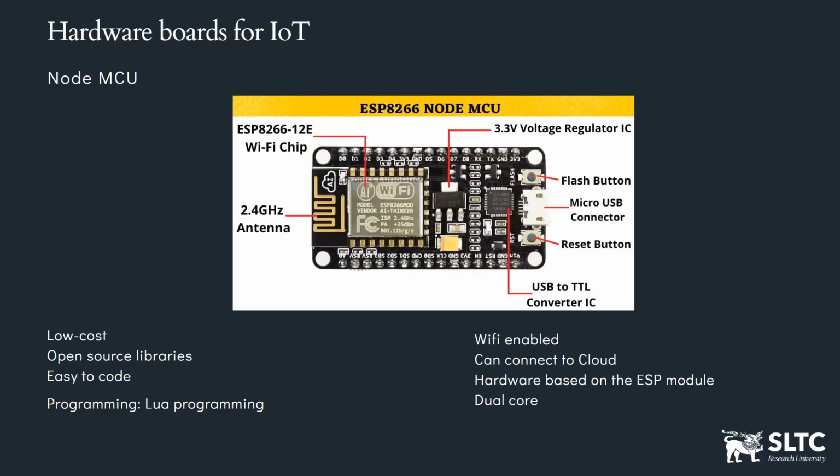And apart from that, it is also low cost in the market. And there are open source libraries from which we can take documentation information to develop applications and algorithms in this controller. And also we are using a programming language known as Lua to code in this Node MCU. Also, there's a Wi-Fi module in this microcontroller, which enables us to connect this to the internet.